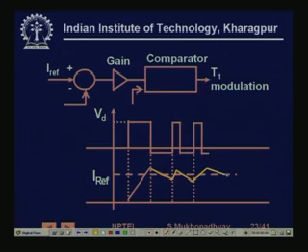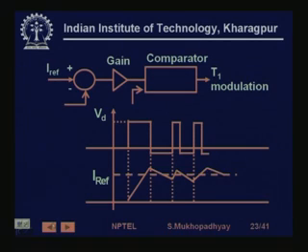So by doing this continuous switching, you can maintain a particular current in a phase, and as we have seen, you can make the motor rotate by a certain angle by controlling the currents in the phases. So this is the basic idea of micro stepping.